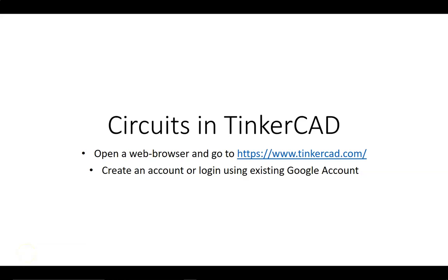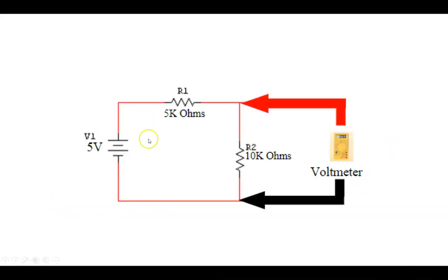All right, so today we will learn about using TinkerCAD to build circuits and simulate them. So we'll do a couple of things. We'll first learn how to create an account, and then next we'll learn how to build a simple voltage divider circuit like this. Use a multimeter function to test the value of the voltage across resistors, how to use the multimeter as an ohm meter, and other instruments that are available in TinkerCAD.